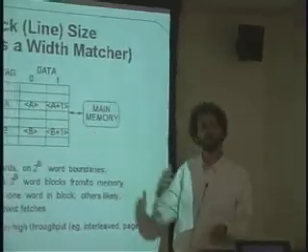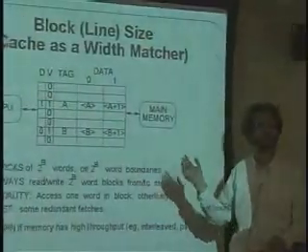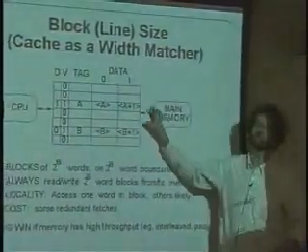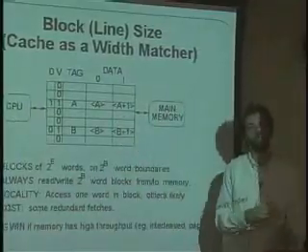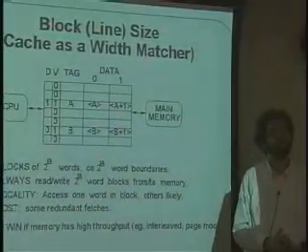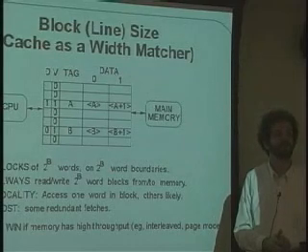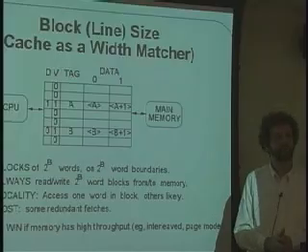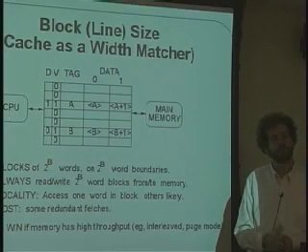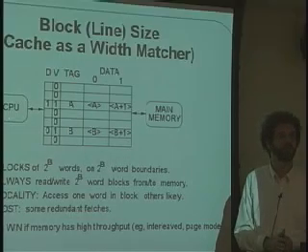So again, we're weighing how long it's going to take to bring in the extra words. We're weighing how much storage we're wasting by perhaps bringing in words that we don't need. And there's this trade-off where you find just the perfect block size which optimizes the performance of the system as a whole, where you're in general bringing in words that you will probably use, although it's likely that the ones that are far away from the thing you're trying to search for are not as likely.